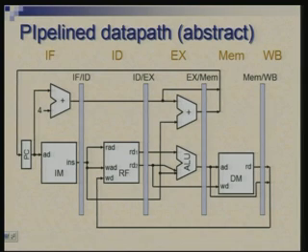Okay, now there is one problem here in terms of how we are starting the next instruction in the next cycle. Next instruction is dependent upon the next value of PC, but the way we have done is that the next address calculation is actually getting completed here, where you are ready to select between PC plus 4 and PC plus 4 plus offset, and that is available only after, suppose this was first cycle, second cycle, third cycle.